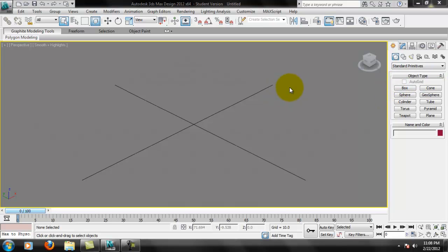So it's kind of like AutoCAD, how they've spread things out. But in order to eliminate any confusion, for now we're just going to focus on this area. We're going to ignore pretty much everything up here. There are going to be some exceptions, but for the most part, everything that we need is over here. So right off the bat, you can cancel out all of the anxiety from the stuff up here and focus on this. We'll also focus on this area. This controls your view settings, viewport windows, zoom in, zoom out, perspective, pan, orbit, and so on and so forth.